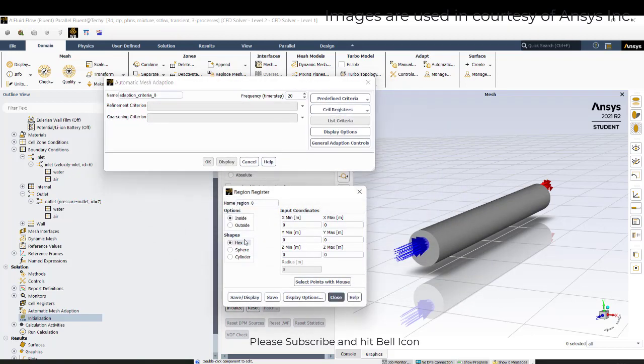In the region you can just select the hex. It will ask for x minimum, x maximum, y minimum, y maximum, z minimum, z maximum. So here we need to play with y minimum and y maximum only. So here we can just check. Maybe for z we can give a random value, -10 and +10. It will not bother you that much. This also -10 and +10.